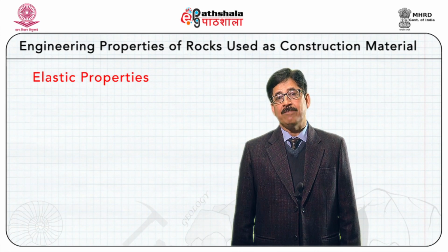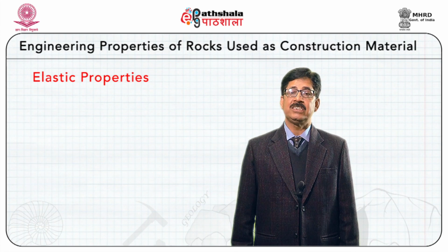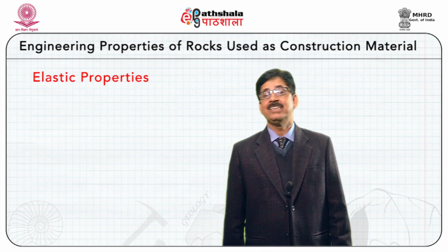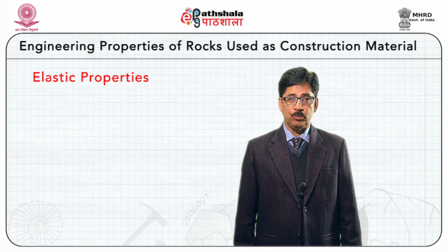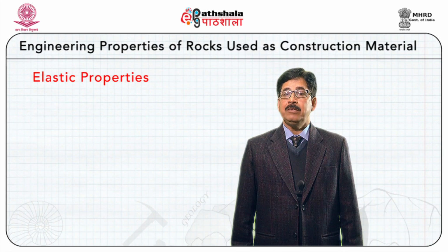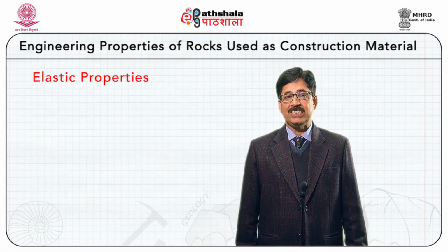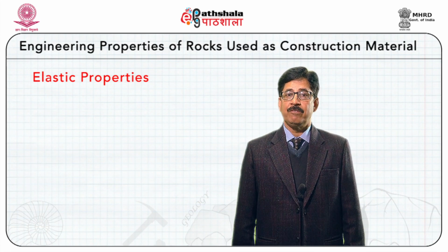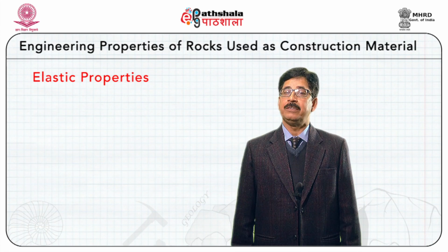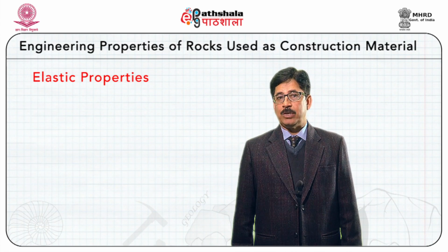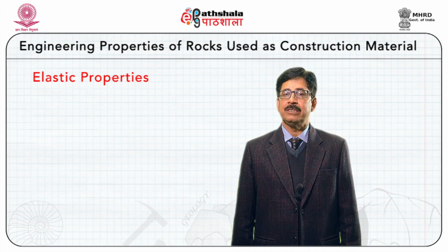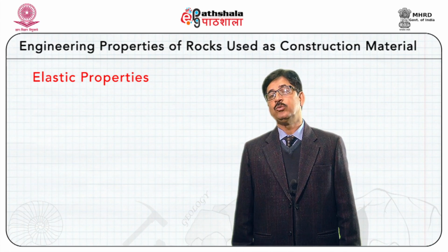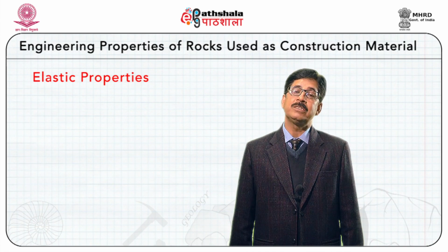Rocks have some elastic properties, that is, they resist deformation. So the level of resistance to deformation can be measured as modulus of elasticity and Poisson's ratio. This can be done by getting data from different stress levels and measuring the strain, and by plotting on a stress strain graph. From there we can get the different moduli, such as the Poisson's ratio and Young's modulus. So elasticity is important, but in building stones we don't have that much load where elasticity of rock is tested. But if you are using the rocks as a rock mass, their elastic properties become important.